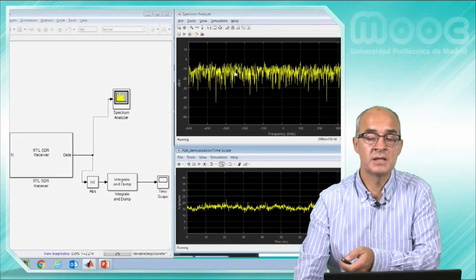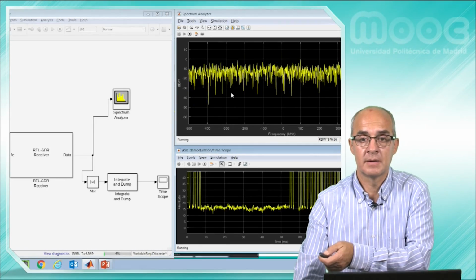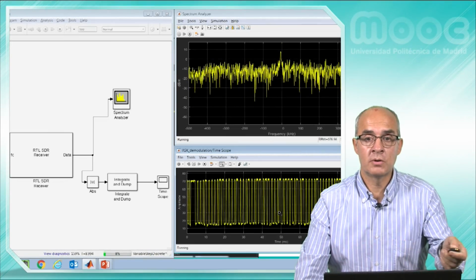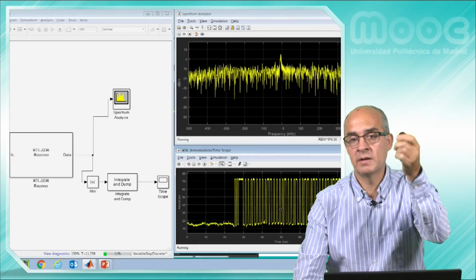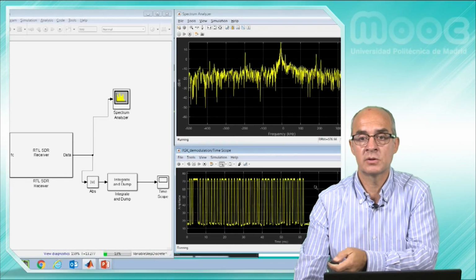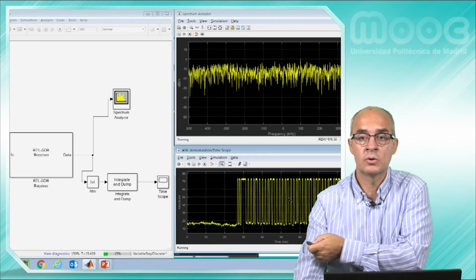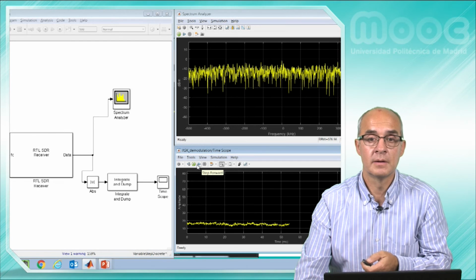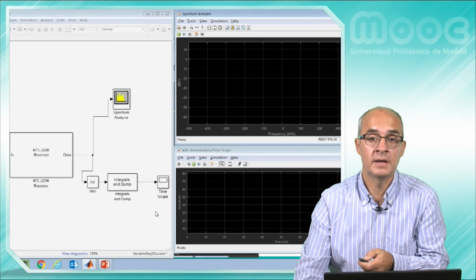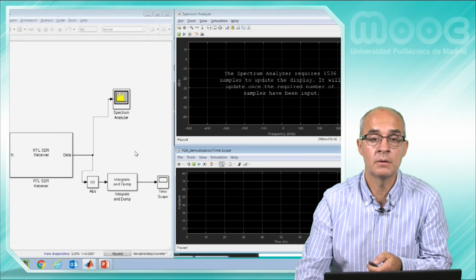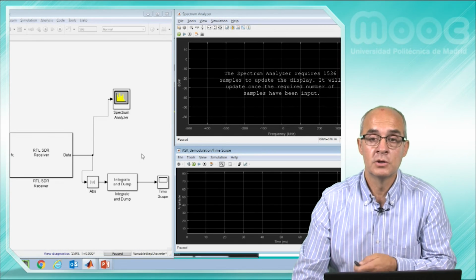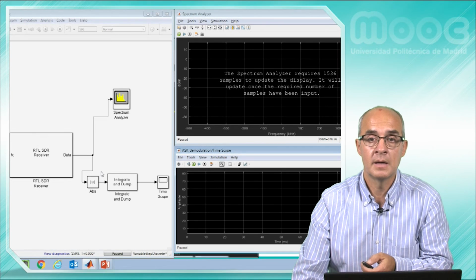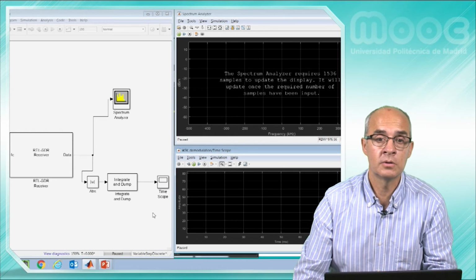Now it's at the maximum gain because there is no signal, and you can see how, when it is receiving, it controls the gain, and even if I move the transmitter, the gain is always constant. So the automatic gain control controls the gain of the receiver and mitigates the effect of the attenuation due to the movement of the transmitter. You can see how important automatic gain control is on this device and how the automatic gain control of the RTL works.